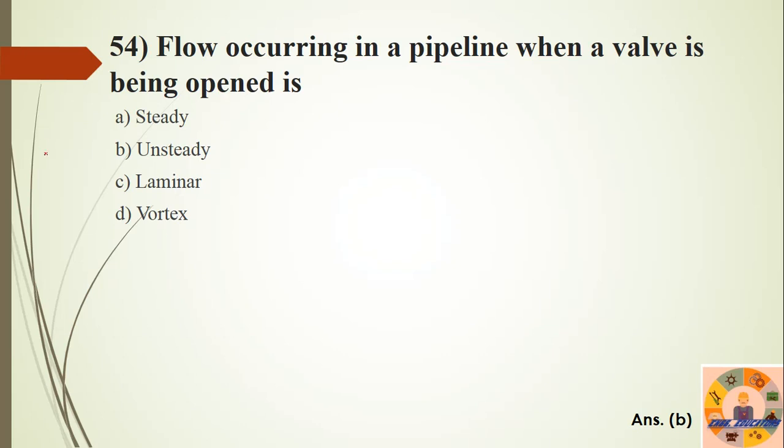The right answer of this question will be option B, unsteady, because it is said that when the valve is being opened, it is a time dependent action, so either steady or unsteady will be the answer, and laminar and vortex will not be the answer because they describe the nature of flow, so these will be opted out.